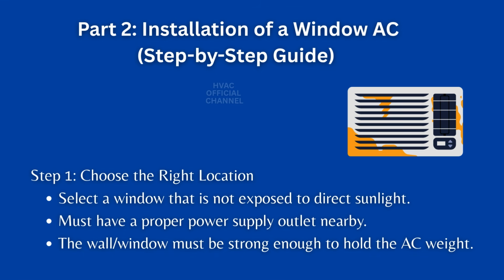Step 1. Choose the right location. Select a window that is not exposed to direct sunlight. Must have a proper power supply outlet nearby. The wall/window must be strong enough to hold the AC weight.